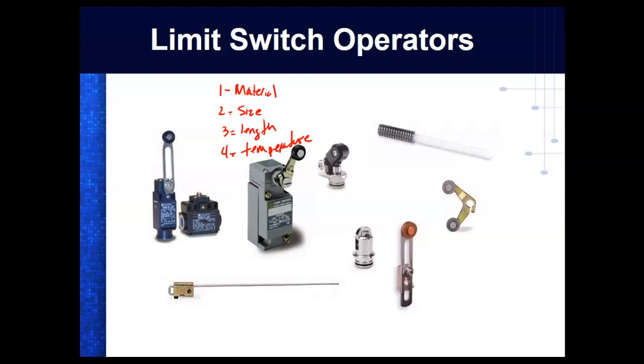And that didn't work. It changed everything, and we couldn't fix it. So, luckily our plane had four jet engines on it. So they had to fly that plane back to Lockheed to get that section of that thermocouple loop fixed. But we didn't know it. We just crimped a regular old terminal on there. And when they fired that engine up, it was interesting.